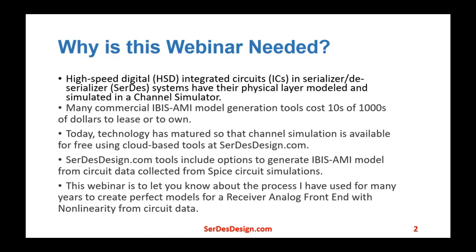Why is this webinar needed? High-speed digital integrated circuit IC serializer, deserializer systems have their physical layer modeled and simulated in a channel simulator. Channel simulators are designed to use IBIS-AMI models that are based on IBIS specifications. Many commercial IBIS-AMI model generation tools cost tens of thousands of dollars to lease or to own. Today, the SerDes channel simulation technology has matured so that it is available for free using cloud-based tools at SerDesDesign.com.